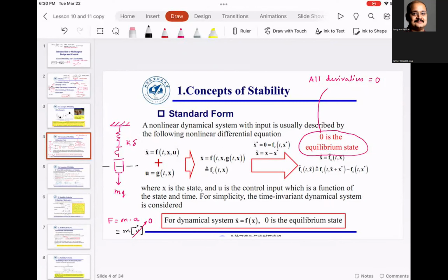But what we want to achieve is the asymptotic stability, which means this Mambo is following, we push, Mambo comes back and then still continues to follow the initial path. Everyone understood this? And it's not difficult. Once I explain the loops that we are going to program in, you will know that programming a flight control system is very straightforward. Online students, everyone understood this?